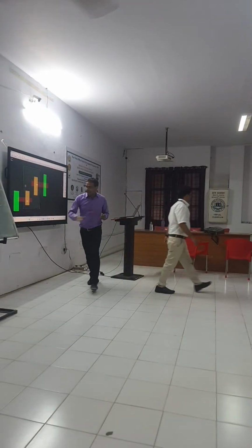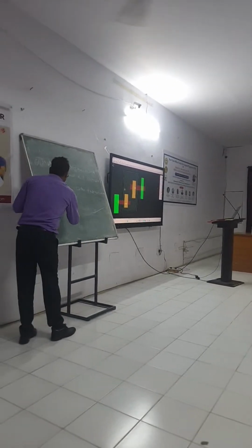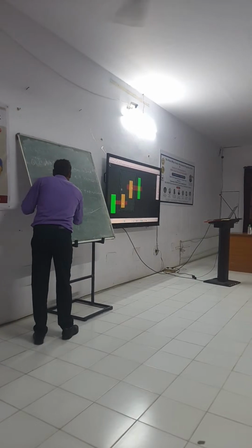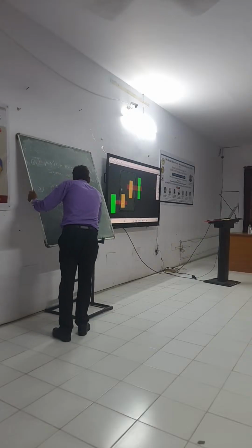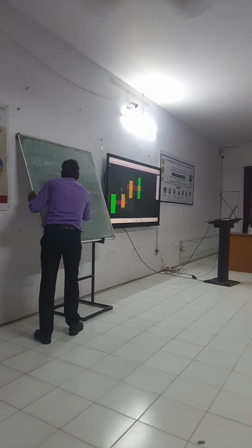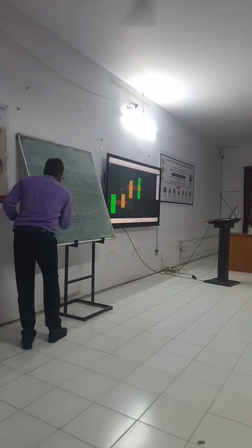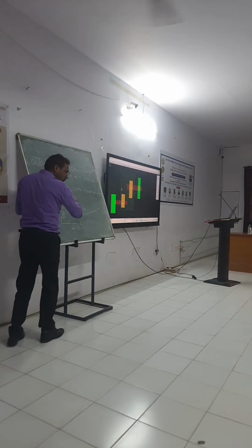So see what I am telling you in short. So I am going to draw the layout of 6T SRAM. So this is your one PMOS, this is the PMOS, NMOS, this is the one PMOS, this is the PMOS. Okay, this is the ground, this one is common, that is the VDD. Here this is your output of first inverter, output of second. So the input of first inverter has to connect here, input of second inverter has to connect to the output here, that is called cross coupled inverter.